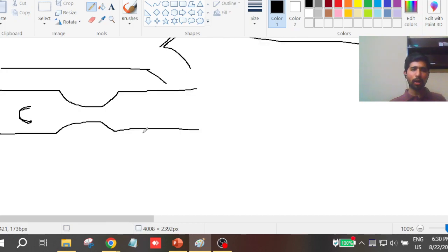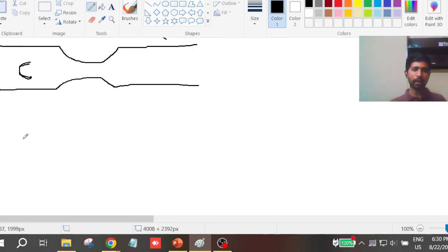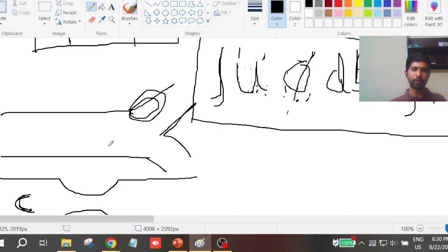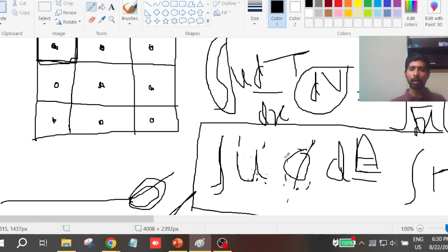Okay, so what will happen there is that apart from your Navier-Stokes equation, the mass conservation and momentum conservation, I have a different equation. It is called a transport equation, just for the concentration of this plug. So now I have a different equation. Now I have to come up with the integral form of that equation and then do some discretization and write code and all.